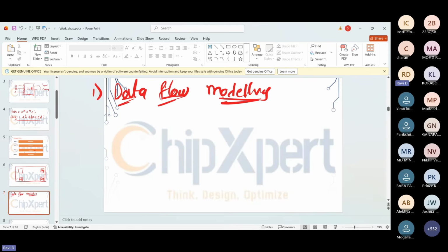So before that, I told you when we use this modeling style, when you know the equation of that circuit, how are we going to design the circuit? The basic structure: first we'll start with module. It is a keyword, and endmodule. This is the basic structure to start any of your RTL code. Module and endmodule is the basic one.